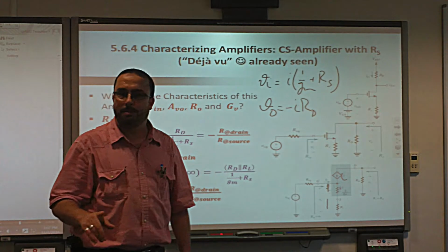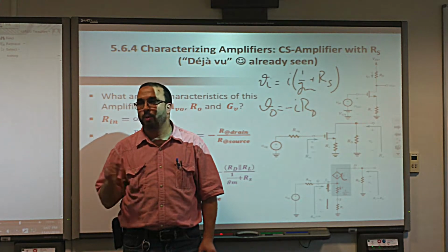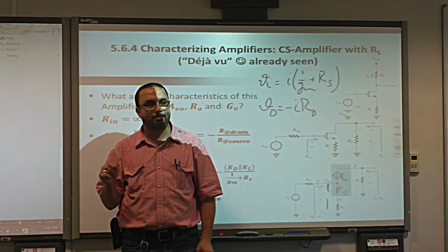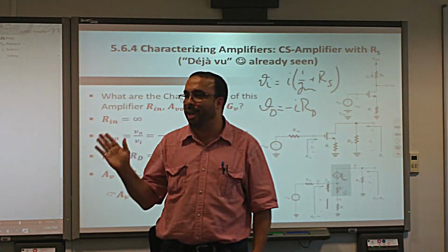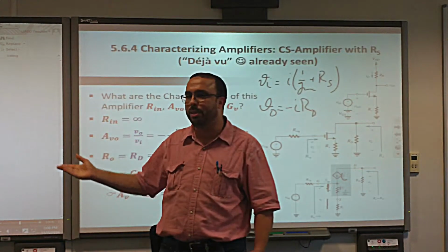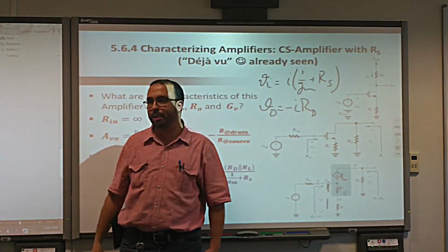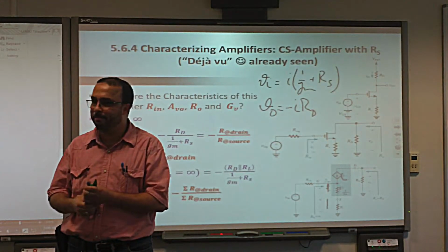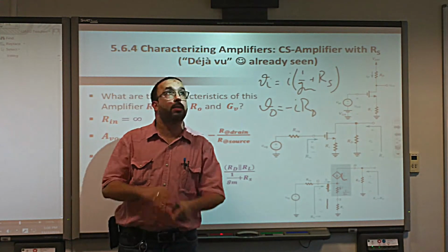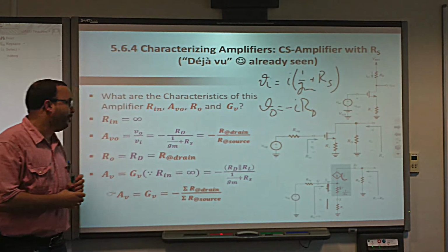Not the DC. We are ignoring something really important in the MOSFET: the channel length modulation. When we put ro, there's channel length modulation. When we don't include it, there's no channel length modulation. Lambda is equal to 0, and when lambda equals 0, ro goes to infinity. It's not about magic. If you don't revise, you find this extremely difficult. I told you since the beginning. It's your call.